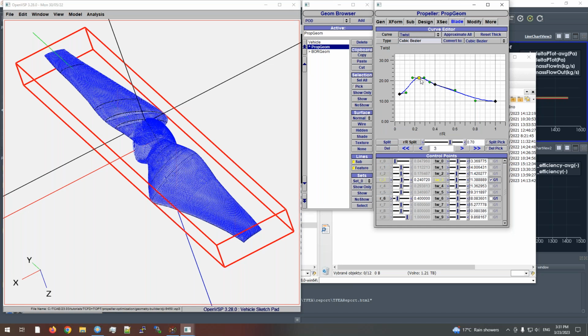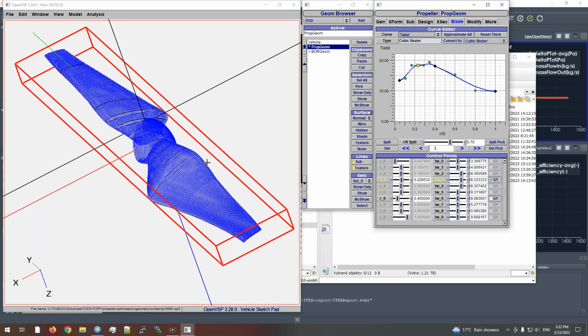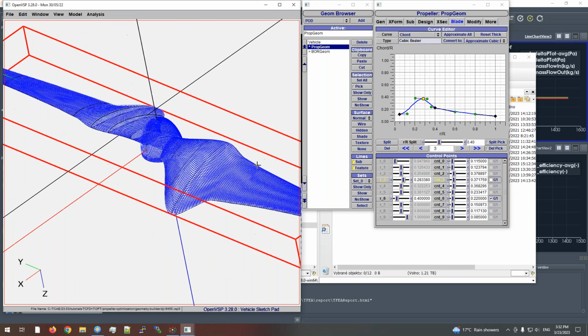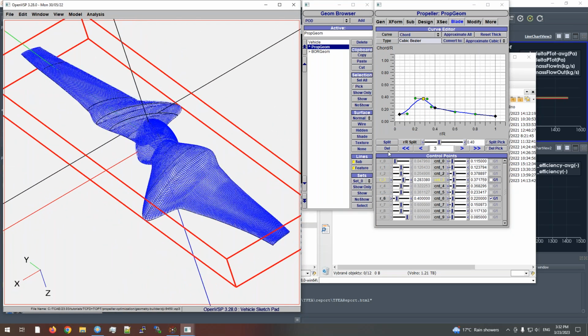If you move the point, or adjust the section, you will see how the blade is changing permanently. All these parameters you can export and use in an optimization loop. For example, the chord length, so I can emphasize the length in this area. This is ugly, but as an example, it's perfect. You can really play a lot with all kinds of shapes and propellers, and even NACA and other profiles. It's a very nice tool